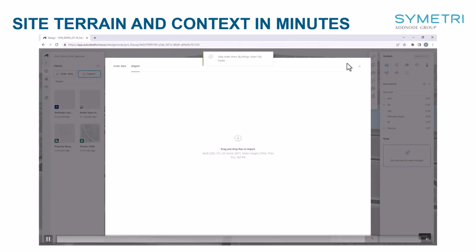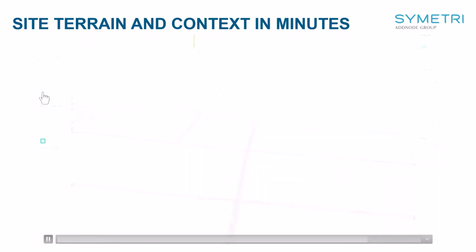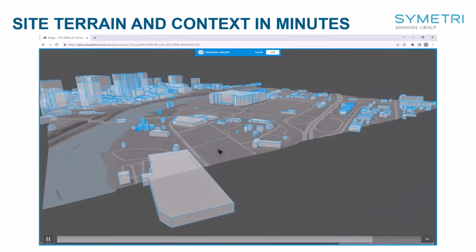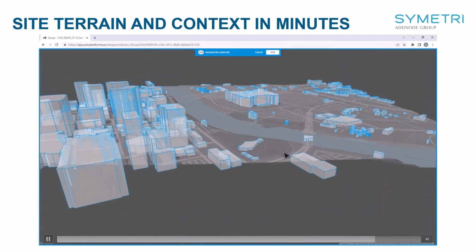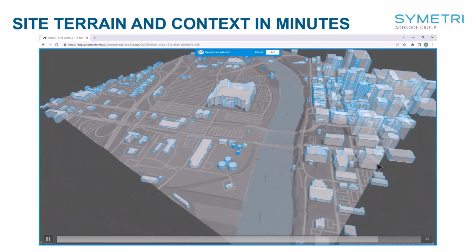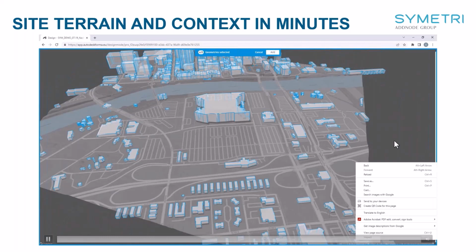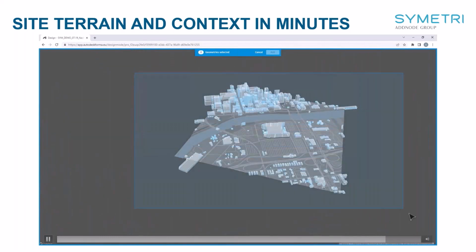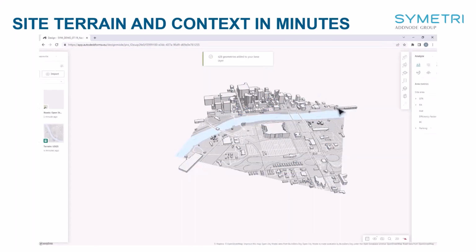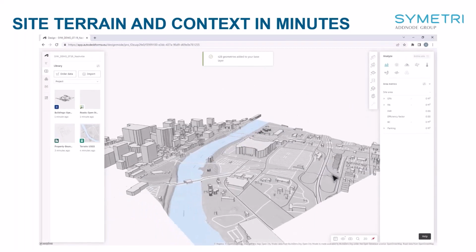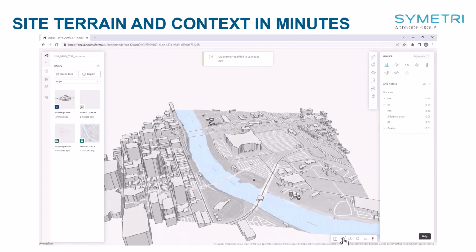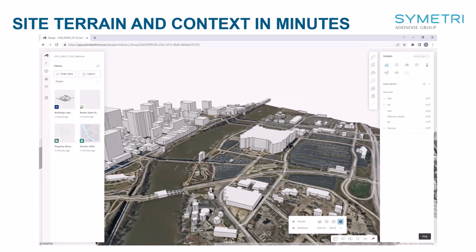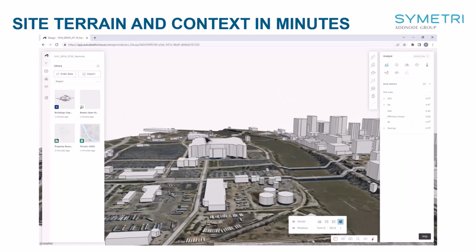Here is the import. We do have the ability to import other items such as OBJs, IFC, as well as images and DXFs for like property lines, 2D vectors. All right, so our buildings are done. Again, it's as easy as selecting everything and adding it to your project. And you're done. That's a full-on BIM model created and ready to go.